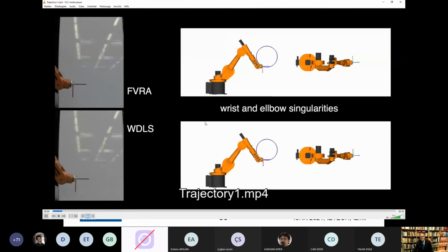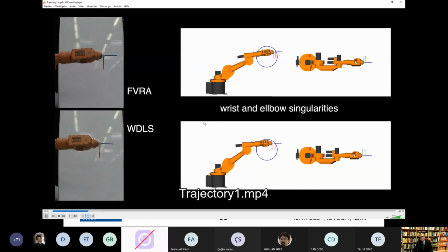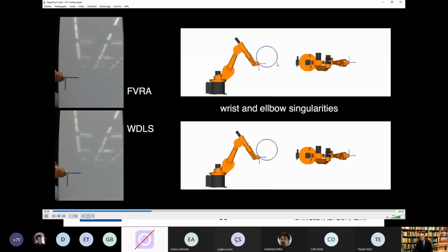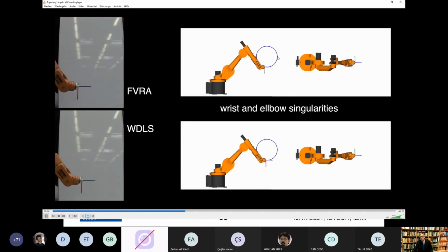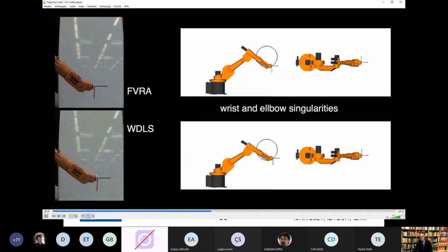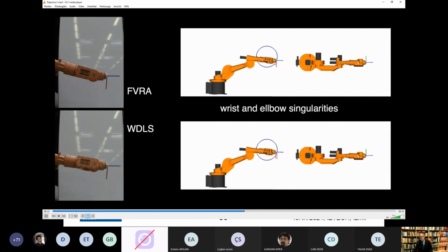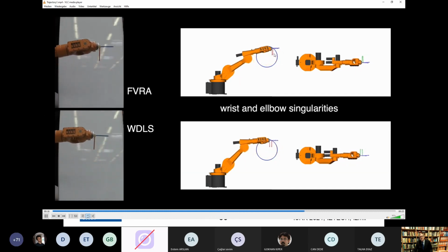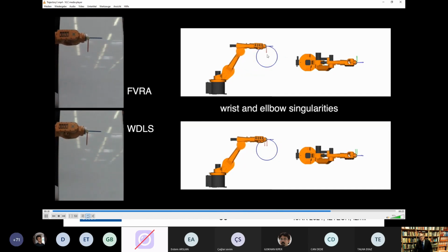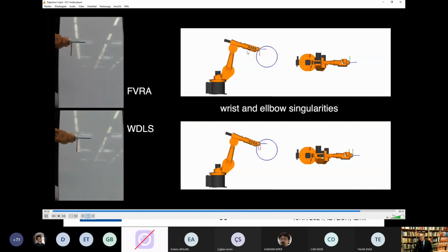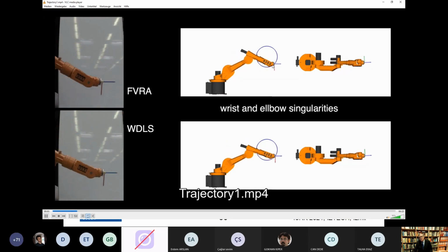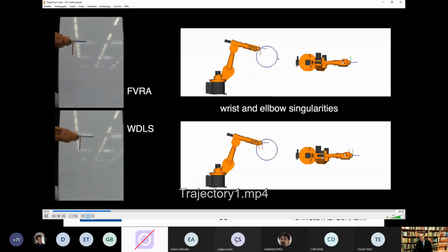My bottom line is that here, for example, you see a case where the target circle cannot be reached by the robot about here. If we use this so-called virtual redundant axis method, then the whole error is concentrated in the longitudinal direction, which cannot be achieved, and this virtual joint just swallows this error.